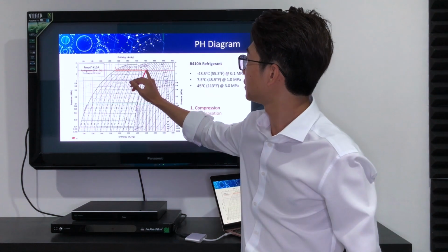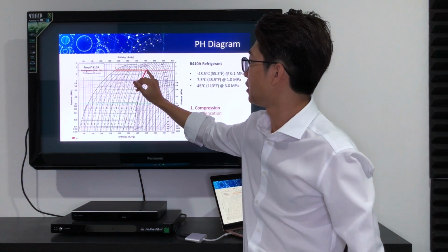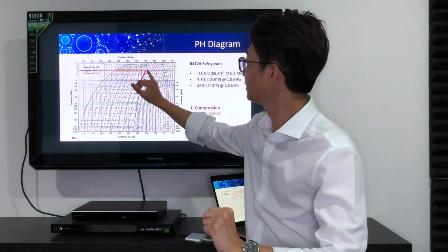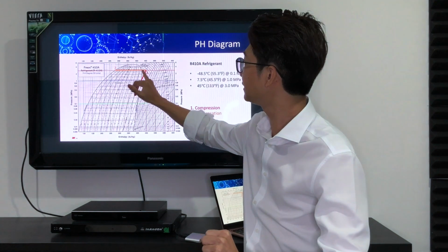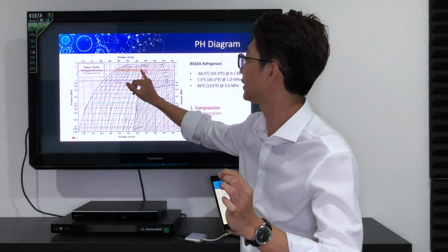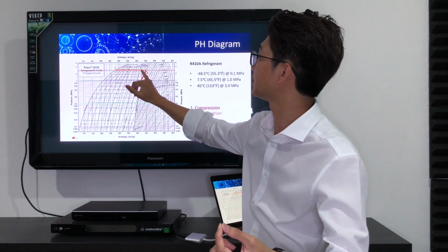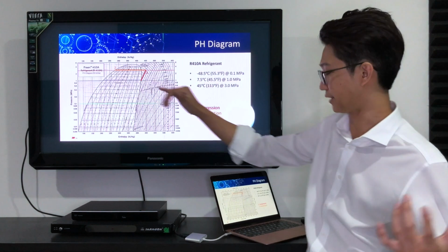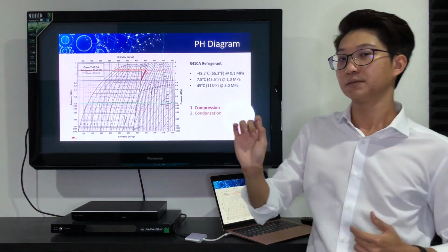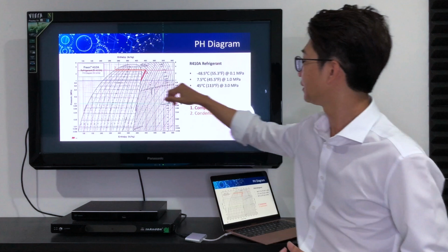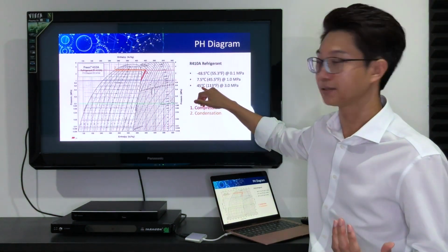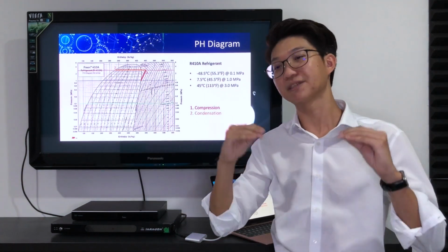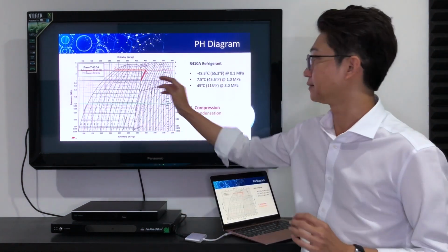You see from here, if you look closely, actually the temperature will drop sharply because everything here is gas. So you take away the heat, immediately the temperature will drop. Then here again, you hit the point where condensation starts to happen. So here you can see the temperature will be constant until it hits 100% liquid, right? Then at this point, the temperature is still very high because the phase change from inside, outside also the same. Phase change, the temperature remains constant, doesn't change, right?